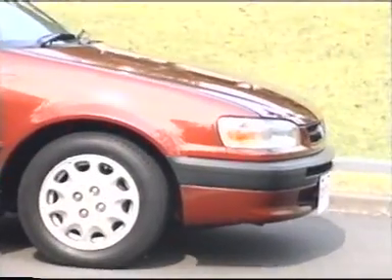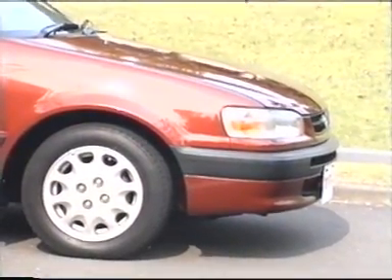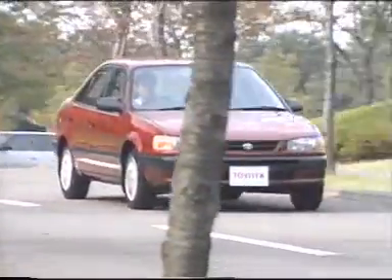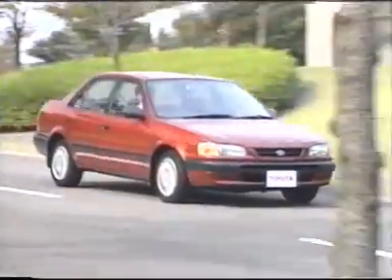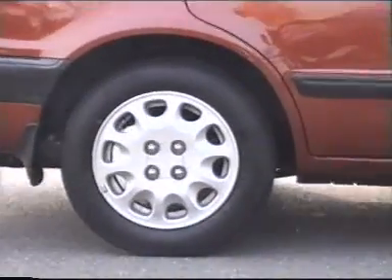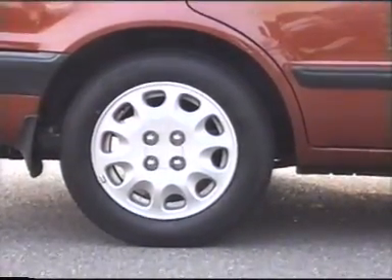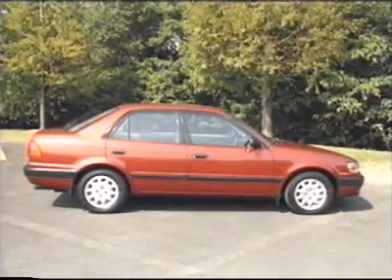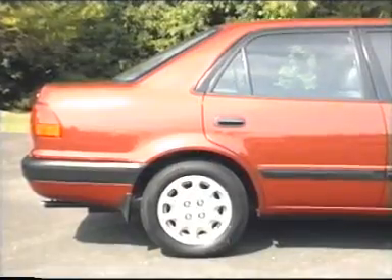When braking, a larger load is generated at the front than at the rear of the vehicle. Therefore, if the vehicle tries to brake the front and rear wheels with equal force, the rear wheels, which are subjected to a smaller load, will lock up early, and the vehicle will become unstable. To prevent this, the brake force applied to the rear wheels must be adjusted.